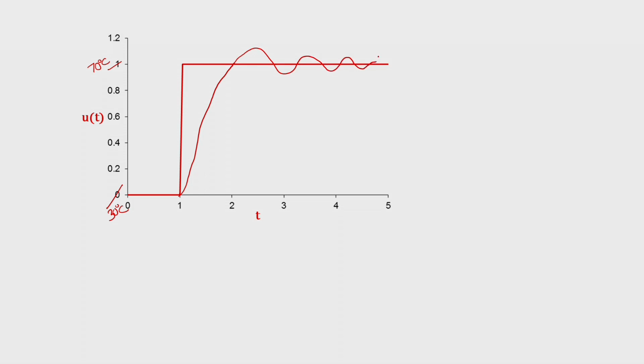Just think about that measuring platform. Suppose you have a dial gauge to show the reading. This is the dial gauge and this is your indicator, initially showing 0. Now because of this sudden load that you have imposed, this indicator is going to move. Suppose this is 70. Invariably we will say that the indicator, because of its own inertia, will cross 70, then try to come back to the 70, and in that effort it again crosses it in the other direction, thereby oscillating around it for a period of time, finally settling down at, say, 70.